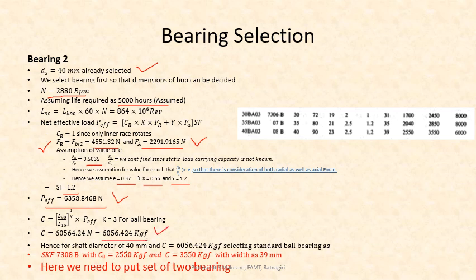kg. Now this bearing has to carry the radial load as well as the axial load, hence instead of a plain deep groove ball bearing, we have to go for the selection of the angular contact ball bearing. Here the requirement is much higher. Okay, and the available standard angular contact ball bearing for a 40 shaft diameter, its capacity is